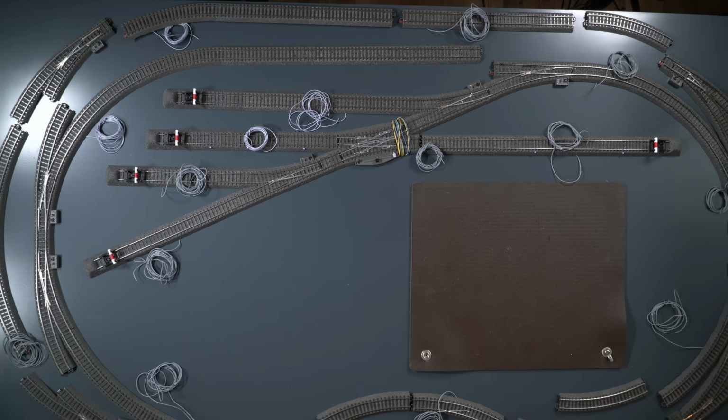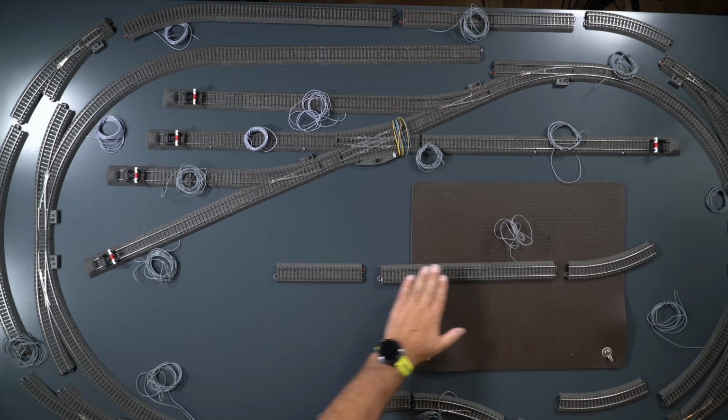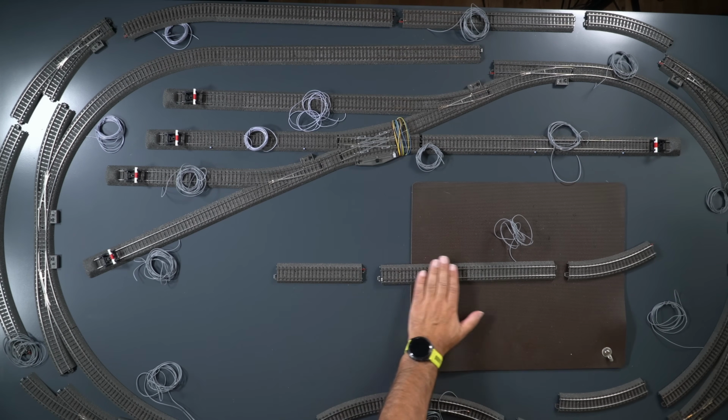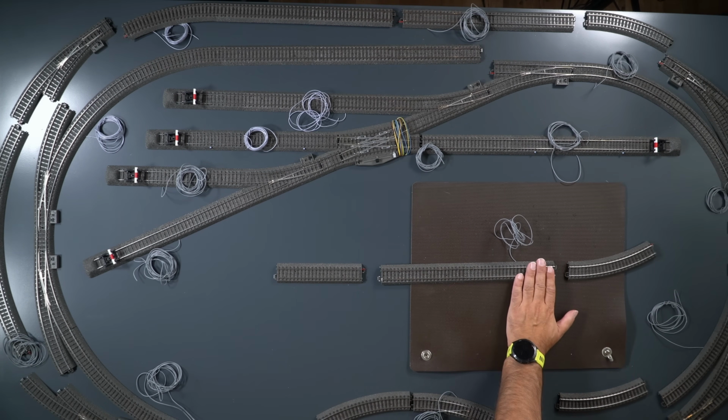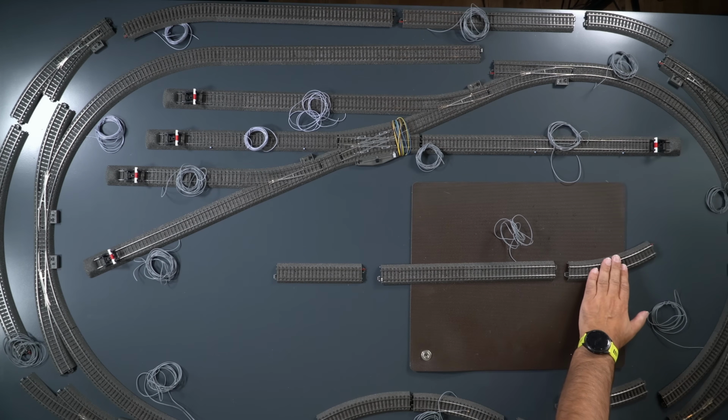We will now work on signal section 1 on the test layout. We'll use this as a representative example for all the others to explain the principle of the stop section with the brake module. For this, I'll take the 3 responsible circuits and bring them to the front. That means in our example, the train comes from here and of course has to brake in this area. If the train accidentally overshoots here because it has such a long braking distance, it will automatically enter the emergency stop area where the locomotive is forcibly braked.